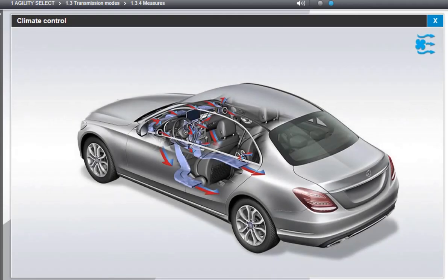The climate control and heating systems of the vehicle perform elemental safety and comfort functions. Their operation is a load on the onboard electrical system and the combustion engine, however. In the Eco Transmission mode, for example, the seat heater and rear window heater output is reduced and the cooling of the air conditioning adapted in order to reduce the energy requirement of these systems to a minimum.